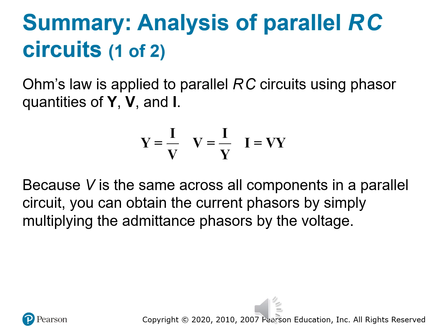We're going to dive into parallel RC circuits where the rules remain very familiar, but the quantities shift names and perspectives. So let's do a quick recap. What changes in parallel? In series circuits, you calculate the total impedance using Z, voltage across components varies, and current stays the same. But in parallel circuits, the roles flip. The voltage across all the components is the same, and what varies? Well, the currents through each path.